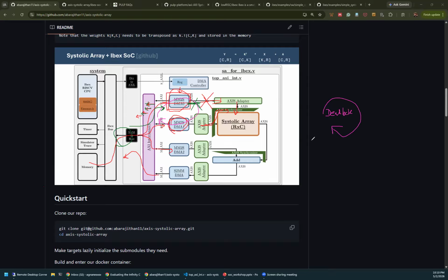It happens for different reasons, but it's a usual problem when you are putting XA stuff, or system on chip stuff, together. You have multiple modules working asynchronously, and at times you might have this situation where everyone starts waiting for everyone, and then you can't move the data through.